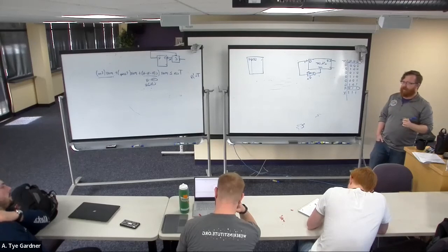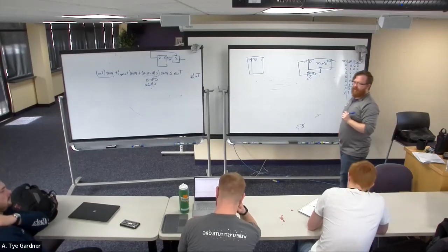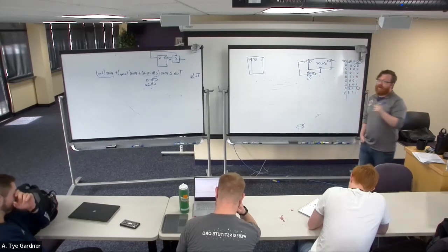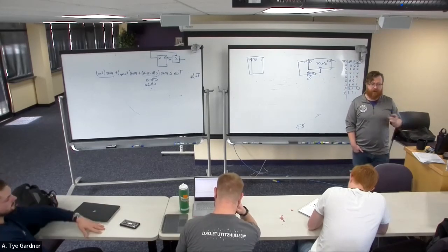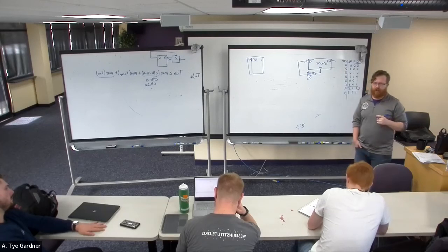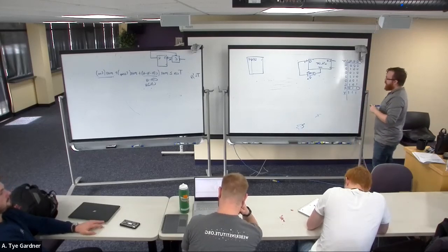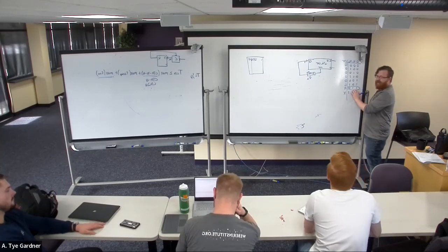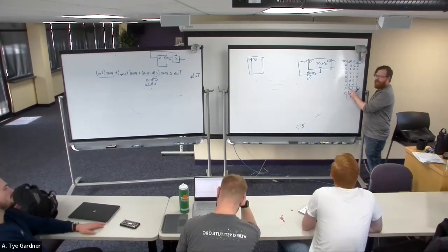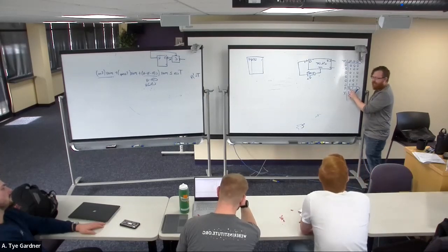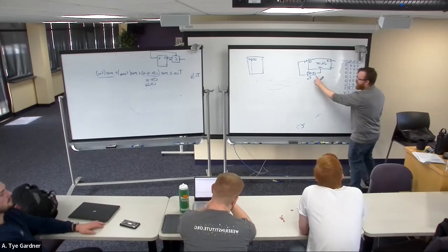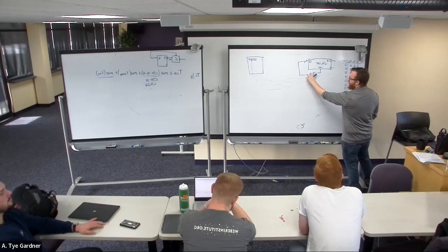So why is that wrong? Because it's not the simplest circuit. And I don't even need a K-map for this one. However, for the more sophisticated ones you might. See how there's a 1 and 1 here? This is the first time that it happens. That 0 doesn't matter. It is literally Q1 and Q2 if this happens. So I can just erase that line.